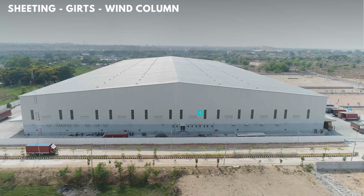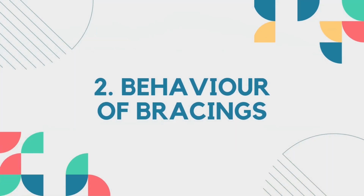We don't worry about the load which reaches the bottom because it is passed on to the pedestal column, but the wind reaction at the top needs to be properly diverted back to the ground. To achieve this, we use the bracing system. In simple words, the load path would be sheeting, wall girts, wind column and bracings. That's all about the load path.